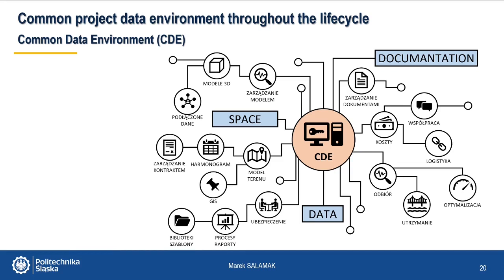BIM methodology is always accompanied by the so-called Common Data Exchange platform, abbreviated as CDE. The CDE platform is usually specialized software that allows access to design documentation with BIM models to all authorized participants of the construction process and is used to improve communication between them.